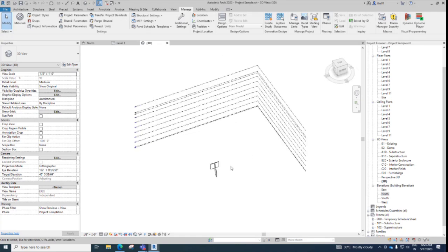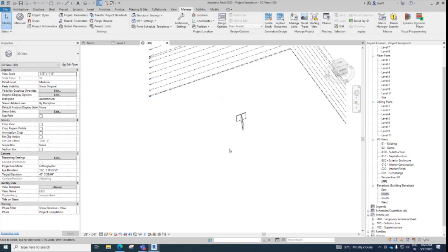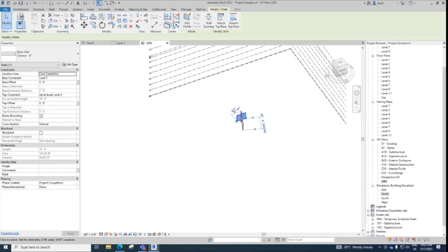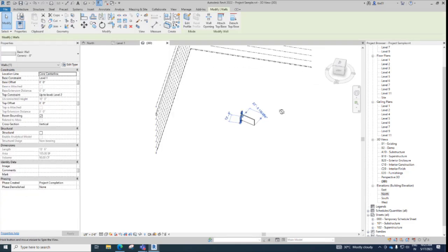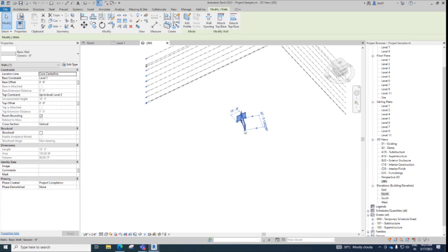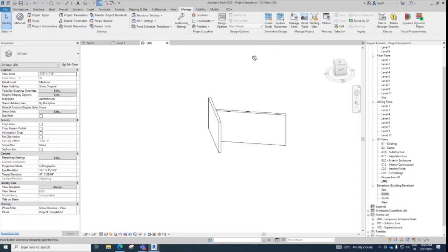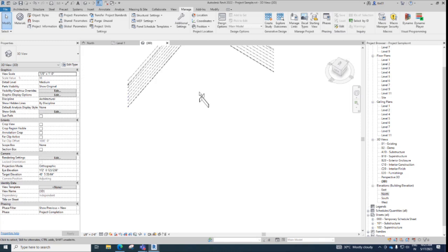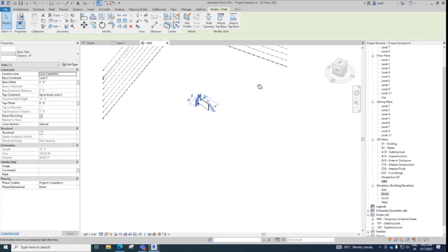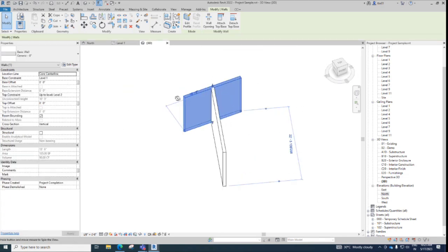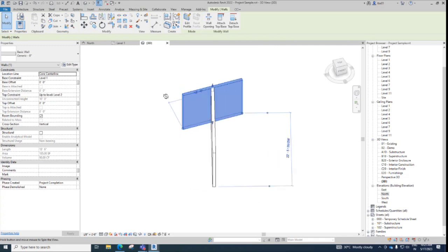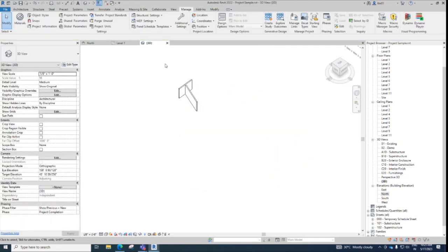All right. And if you want to orbit with respect to any object, you select the object and then you shift and orbit, so that object will be placed where it was and the entire window will move along with it. If I don't have anything selected and I shift and orbit, things will go a bit haywire. If I am zoomed out, it will go a bit haywire. If I have something selected and I zoom in, it will always be in the center and everything will zoom in, keeping that in focus. All right. So these are basic navigation tools,